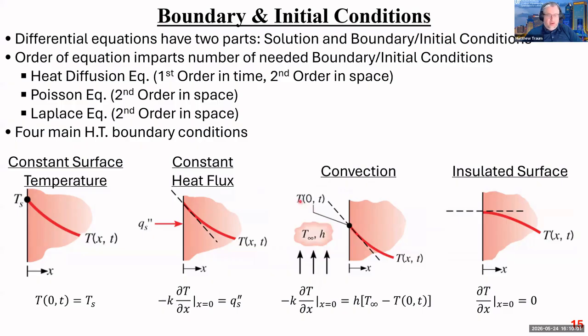And so the temperature at that particular spot at all time is basically set by equating the conduction out to the convection into this gas that's blowing past the object. That's represented mathematically here, right? Here's the conduction through Fourier's law, which is leaving, and then here's the convection, which is absorbing that same thermal energy. They're equal to each other. And so you can also use this as a boundary condition.